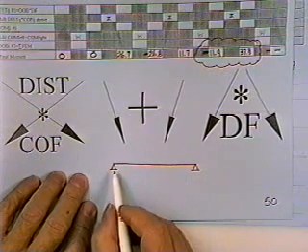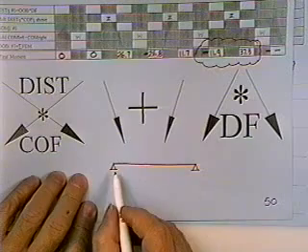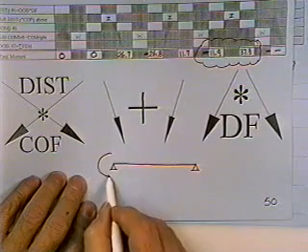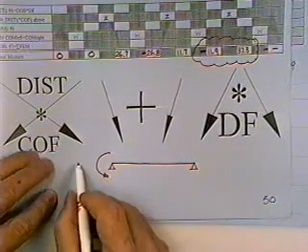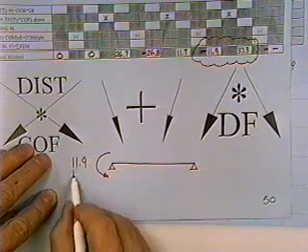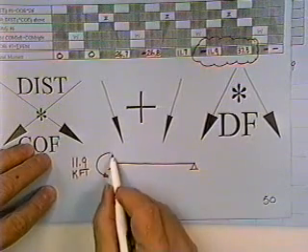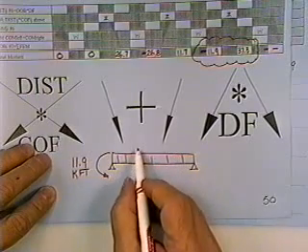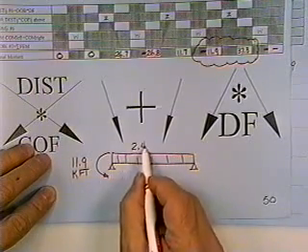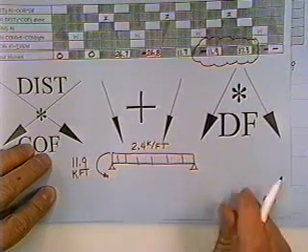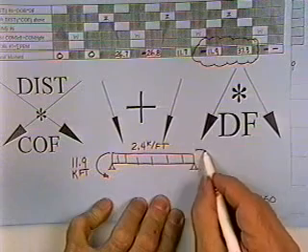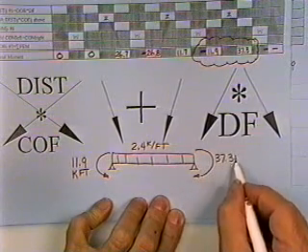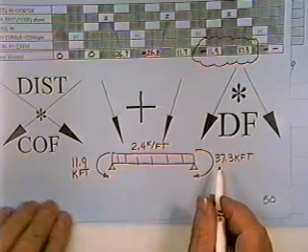It has a moment of a minus 11.9, which is a minus, means it goes this way, and the bending moment is 11.9 kip feet of moment. It has a uniform load across its top of 2.4 kips per foot. And it has a moment on the right-hand end positive, and therefore that is 37.3 kip feet of moment.